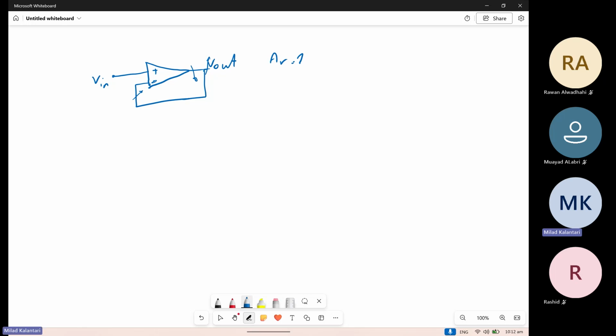And then we realize for the op-amps, once it is in a negative feedback mode, basically the op-amp tries to minimize the input voltage. The input voltage means the positive port and the negative port, basically that it tries to make it similar. So in a negative feedback, V in plus of the op-amp will be equal to V in minus of the op-amp. And then this is the way that we actually use this to solve the op-amp circuits.